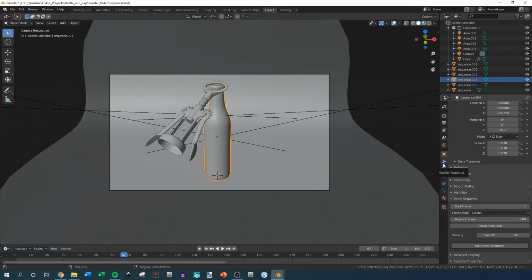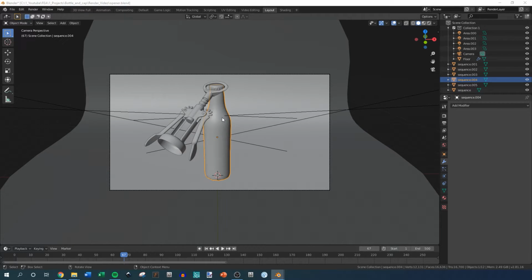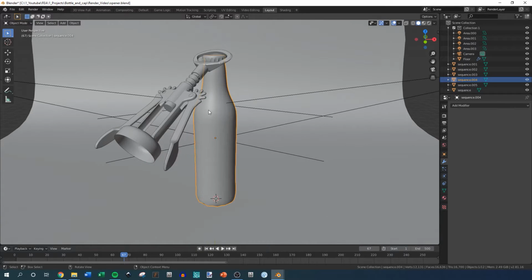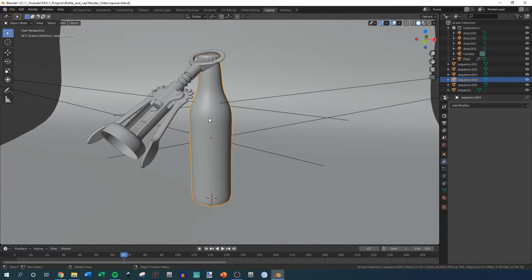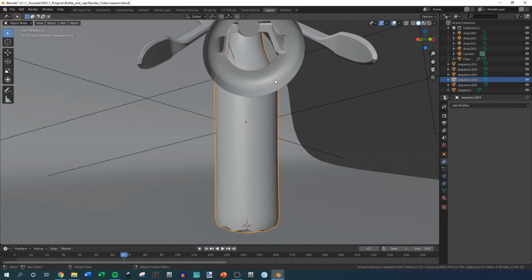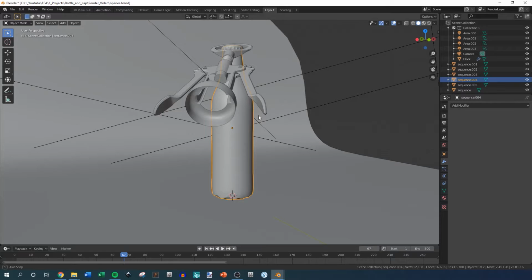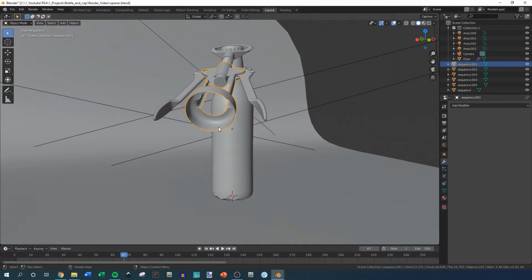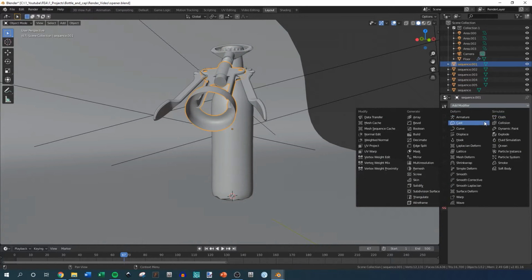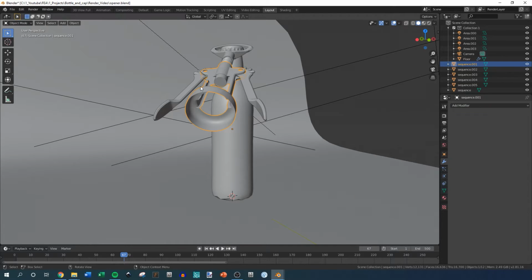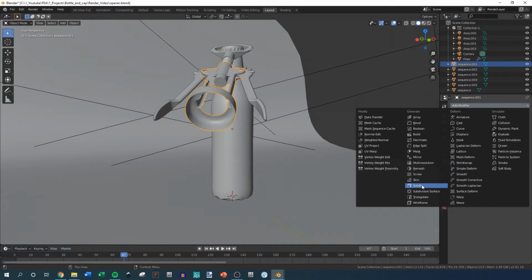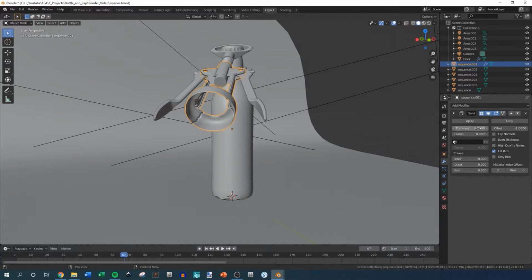And what else? The next one is modifiers. This one's important. It's going to allow you to modify your objects. And what this means is if you have something like I've got, where these are shells, see how this is like a shell? You can add a modifier to it to make it a thick shell, to visualize. So if you have a shell and you want it to represent whatever thickness you have in your simulation, you can click it, go to add modifier, solidify, and then you can apply a thickness.